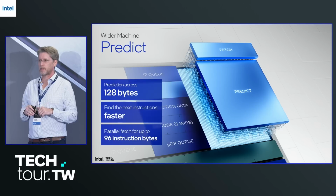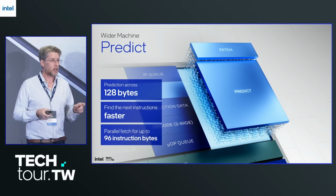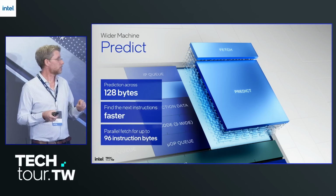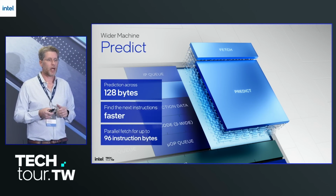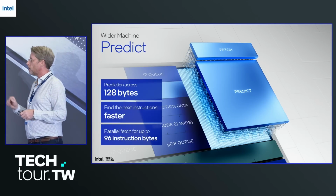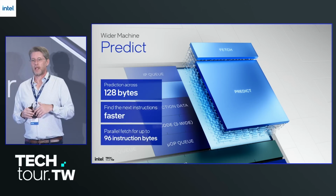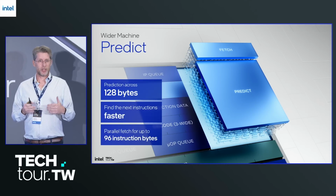This helps us fetch the data faster as well. Because we know where we're going, we can start the access. So if we're going to get the data out of the cache and send it to the rest of the machine, now we can do that a little bit quicker and more reliably. Here, we can get up to 96 instruction bytes.